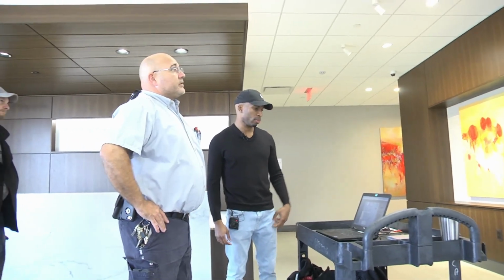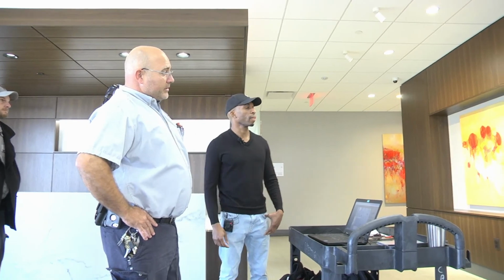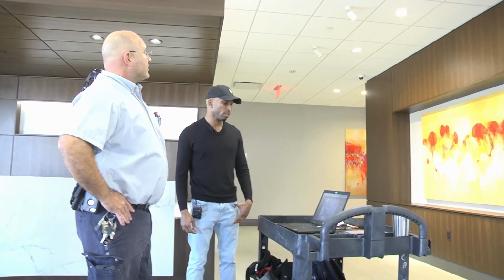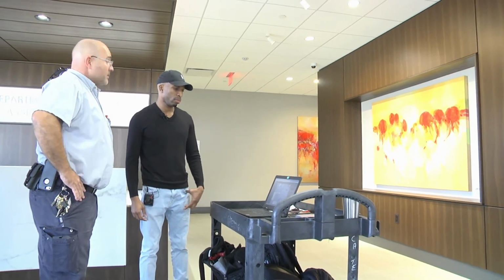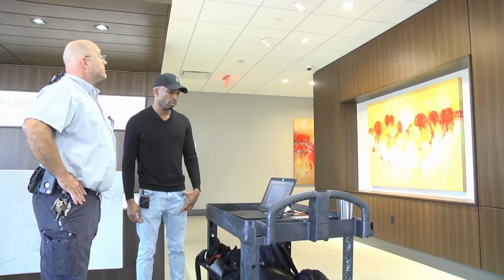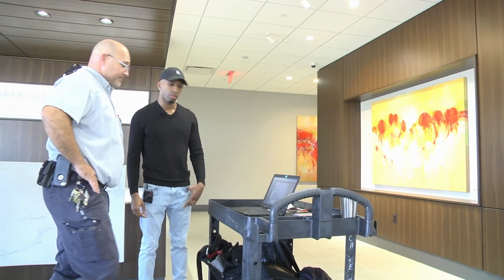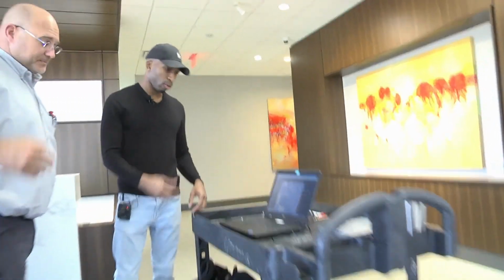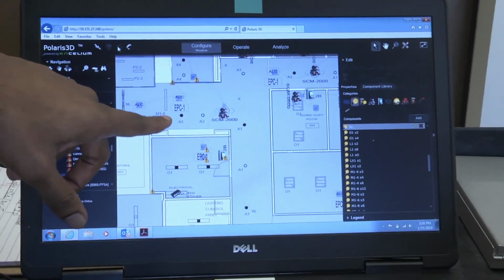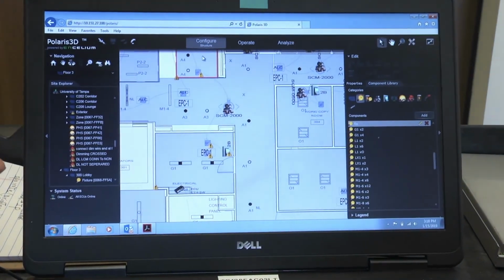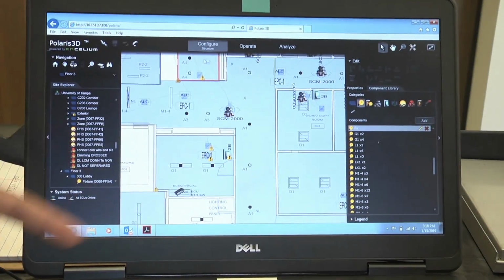All right, we're here on the 3rd floor outside the elevator lobby for the portrait photo addition to tie into the Encelium system here. Now we'll have to install them. Okay. So if you come over to the first step, we're going to be adding a component, because right now the area is right here and there's no fixture template there. So we're going to use a template from our template library and put it there.